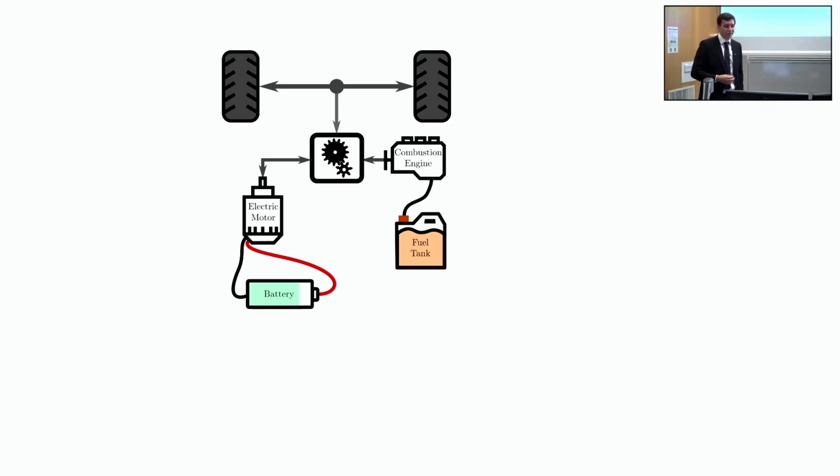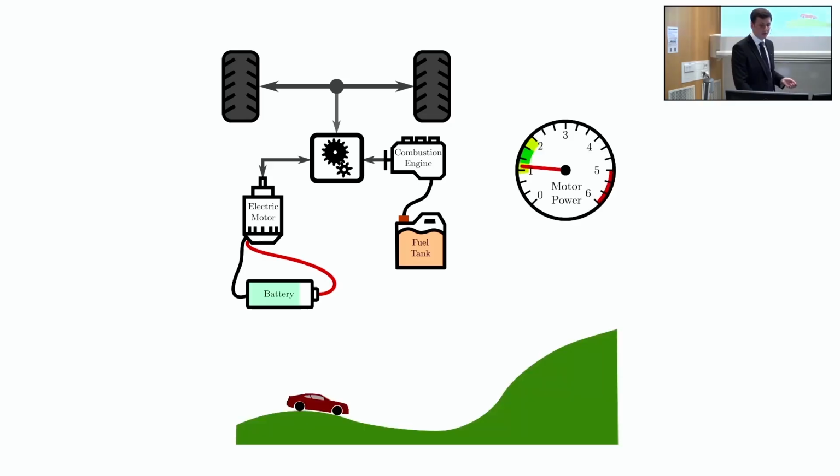When I started this 6 years ago, my impression of hybrid electric vehicles was you use the electric motor to get to work because you have a short commute and the battery lasts, but if you want to drive further, you would start up the combustion engine so you can get longer than the battery allows. In practice, that turns out not to be the case. I think it's very uncommon for hybrid electric vehicles to completely switch between the two. You essentially always use both. In fact, this thing where you plug in your hybrid electric vehicle and charge it up is not something a lot of hybrid electric vehicles support. The battery is only there for energy storage. And so you might think, why would you put a battery in a vehicle that you cannot plug in and charge externally? But the reason is you can conserve energy and use it later.